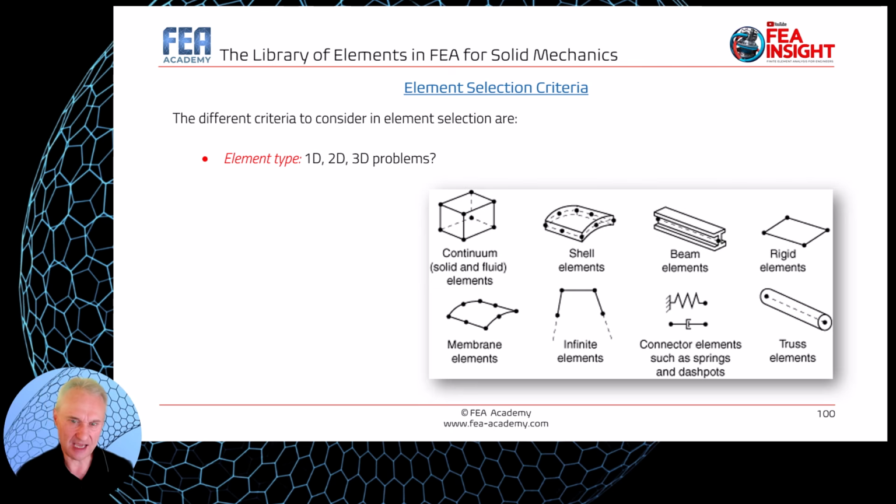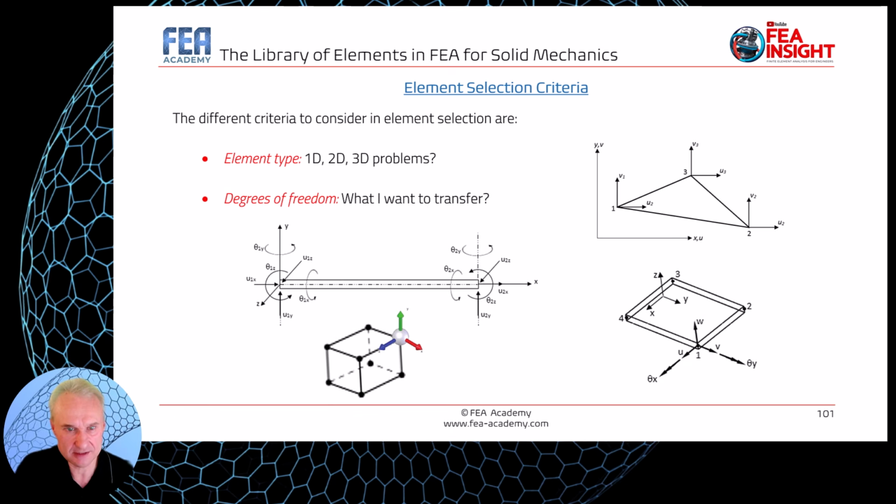But keep in mind that once a part has been modeled using a specific family, it is difficult to change it. So precise knowledge concerning the various available families is necessary before beginning the modeling work. Depending on the structural behavior of the model parts, the computing time, and required accuracy, you must select the elements from one or several families to model the proper mechanical effects.